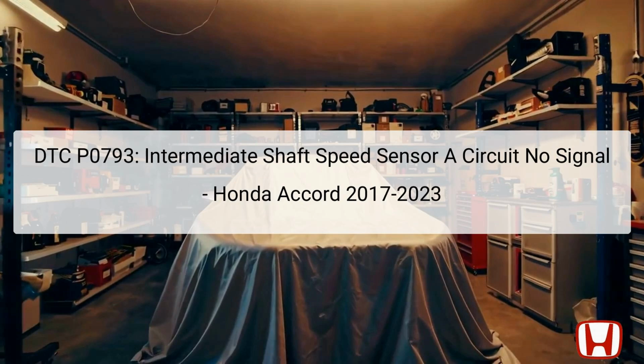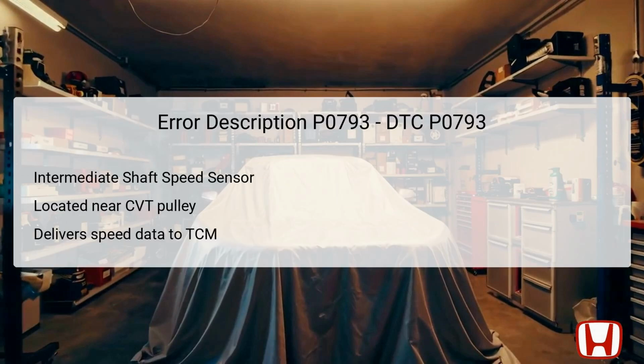Before proceeding with troubleshooting, it is advised to review general diagnostic information to ensure a systematic approach. The code P0793 indicates a fault with the intermediate shaft speed sensor A circuit, specifically highlighting a no-signal condition. The intermediate shaft speed sensor is a critical component that measures the rotation speed of the intermediate shaft in the CVT, which is responsible for power transfer between the engine and the wheels. Its location near the CVT drive pulley ensures that it effectively detects the shaft speed and sends this information to the transmission control module, TCM.